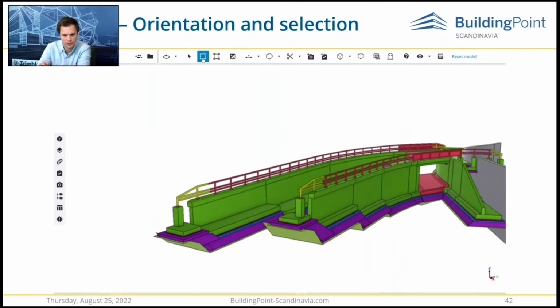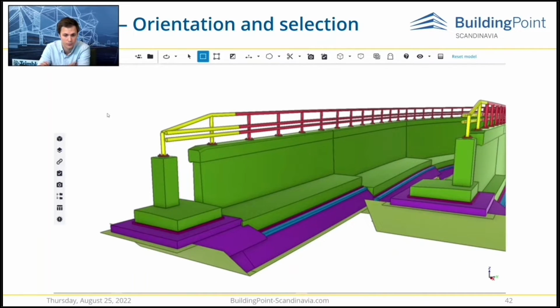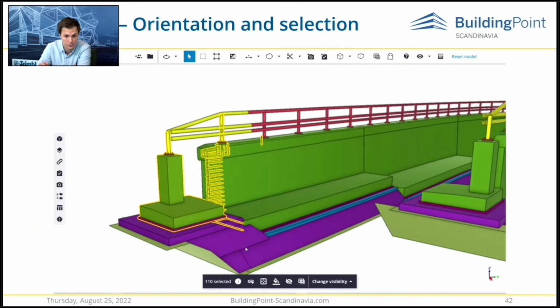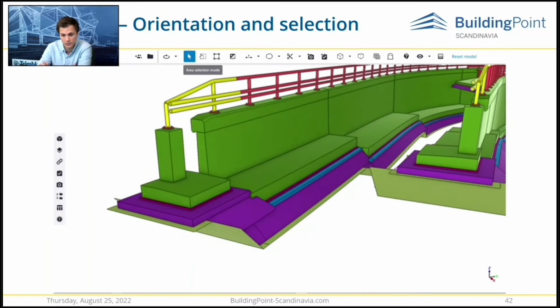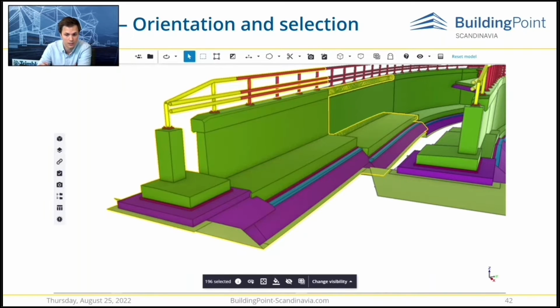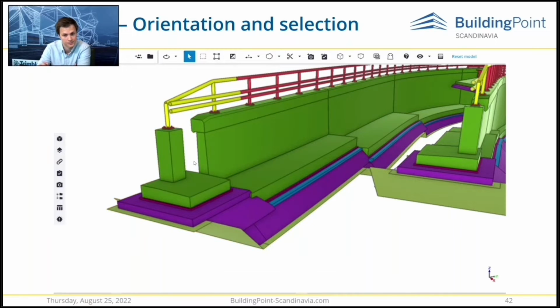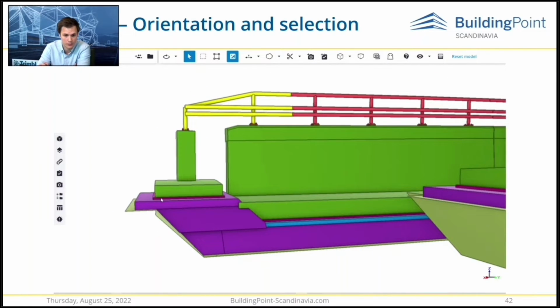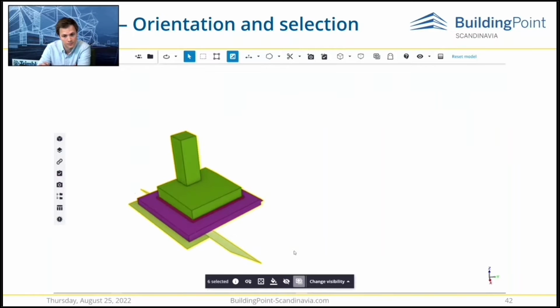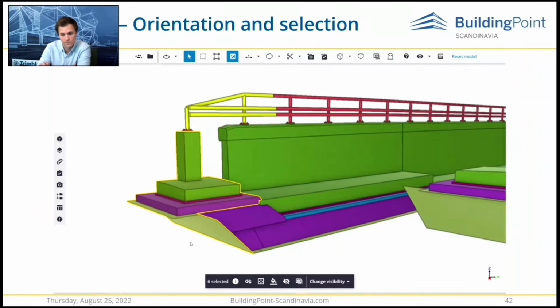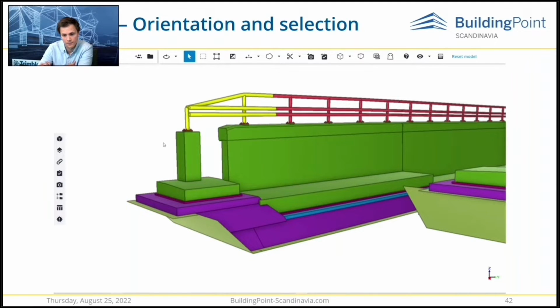We will also show now different ways to manually select objects. We have this usual area select working how we are used to, from left to right. It selects any objects completely within the area. And if we select from right to left, any object touching the edge of the area will be selected. And also, if you're working on a touch screen, when activating this switch, for successive left clicks, you would keep selecting new objects and adding them to the selection. And that was a quick look at different viewer options and how to select objects.